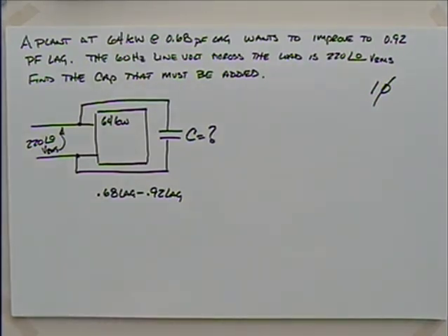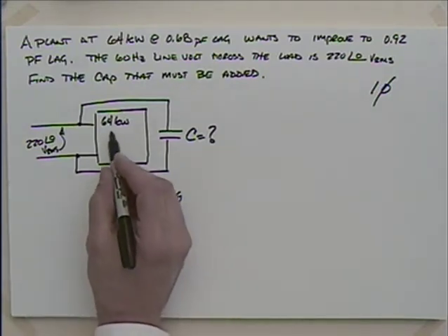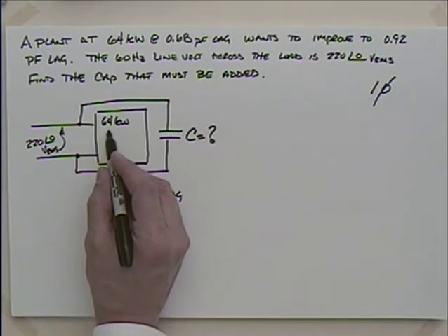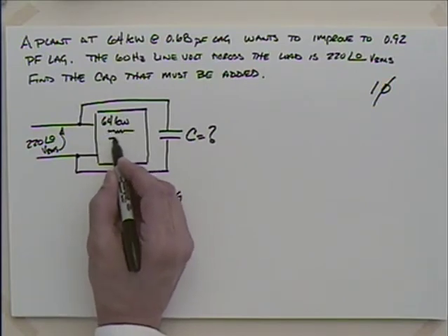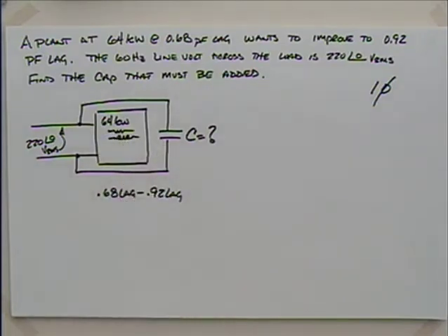Now, probably if we were careful, we could work out what the impedance is in here. But as far as trying to figure out what I have for resistor and what I have for inductor, no one's told me anything, have they? So the best bet on this problem is probably doing it with what? Power triangles, right? Okay, doing it with power triangles.